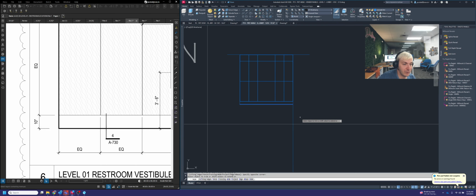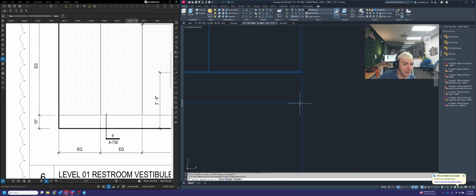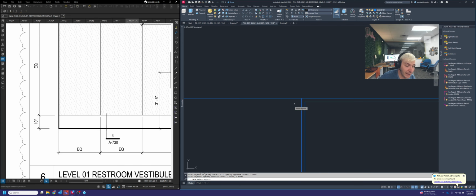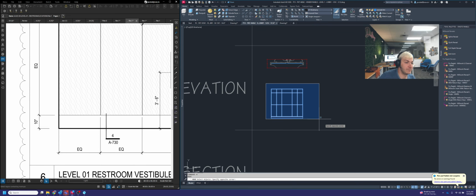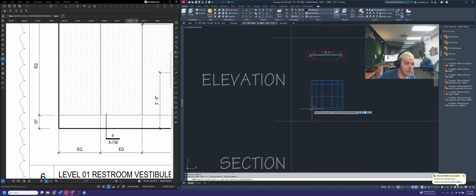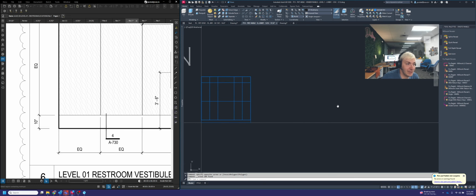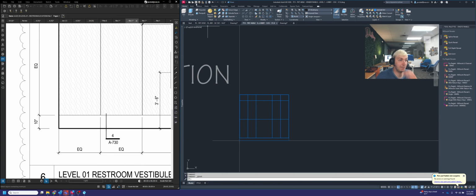And then what we'll do is we'll move the elevation view to where it needs to live in our grid system. And I will pause the video and we will move on to the section views after this. Section views and detail views. Move command, click that corner, snap it there. And then this is my copy of my plan, so I no longer need that. We can delete it. And go ahead and save here where we're at. And we'll stop back in just a moment and finish the sections and details.